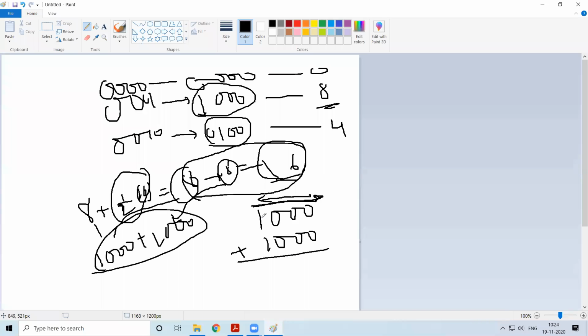So if you just observe 1 1, what is the result? What is the sum of this? Sum of this is 0. Now we have a carry generated from this. This carry should be sent to the next bit. So carry comes over here. So it is 1 plus 0, it is 1. There is no carry. 0 plus 0 is 0. 0 plus 0 is 0. So now I am getting 4. Remember, in bit reversed addressing, you start with the MS bit. You propagate the carry in the reverse direction with respect to regular addition. So then I'll be getting this value.